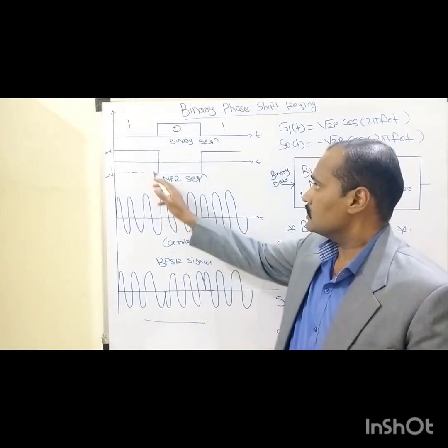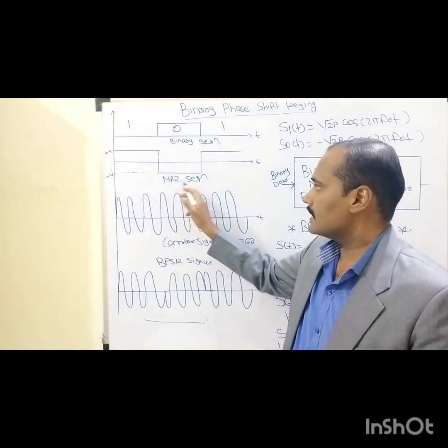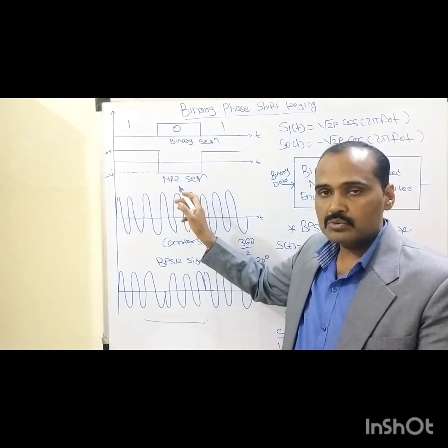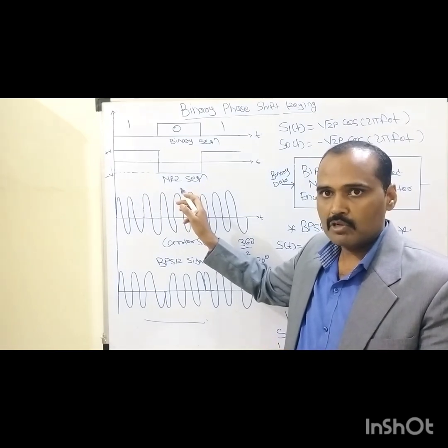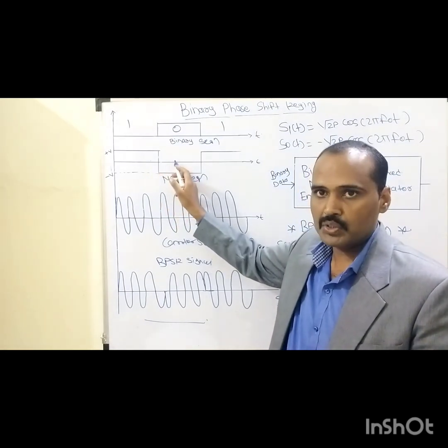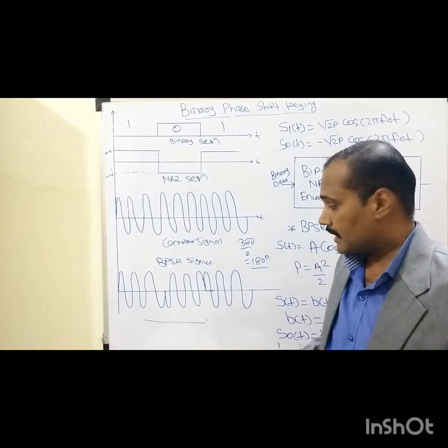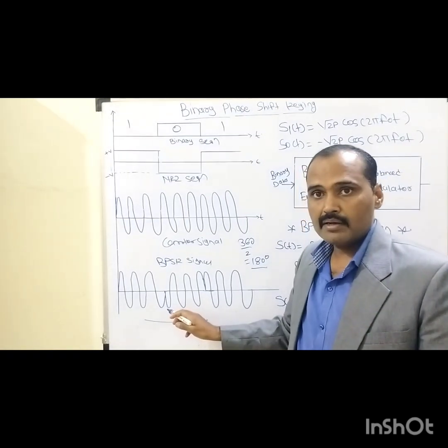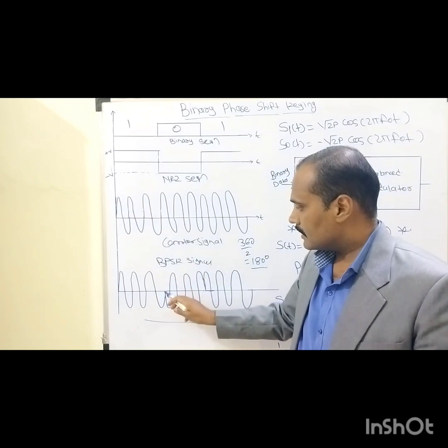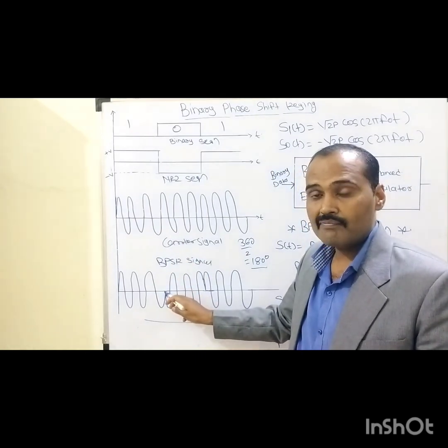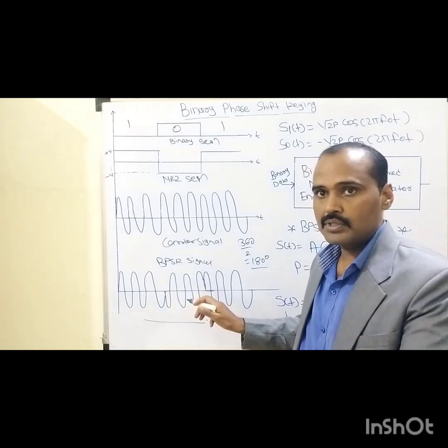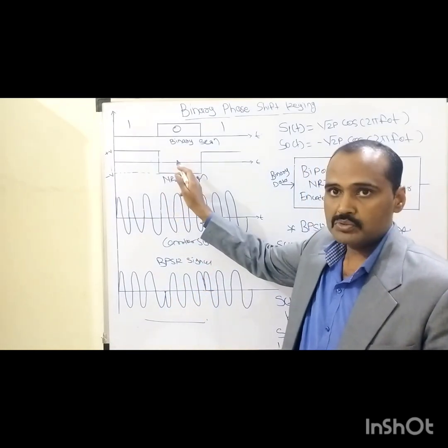But when the signal changes from 1 to 0, as far as this NRZ, or not return to zero bipolar symbol sequence is concerned, carefully see that in this BPSK signal envelope, the phase of the unmodulated carrier signal is changed by 180 degrees below the horizontal reference line whenever we go through the signal transition from 1 to 0.